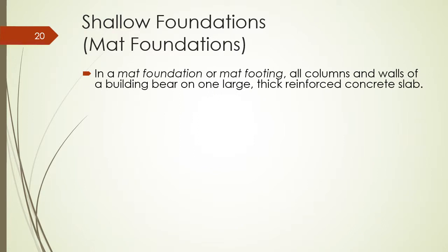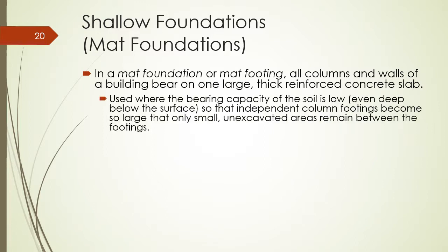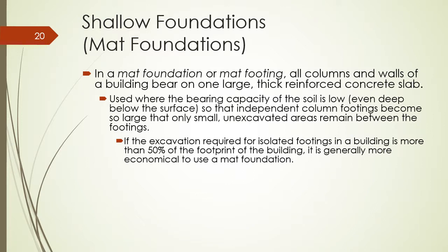A mat foundation, on the other hand, all the columns and the walls in the building will bear on one thick reinforced concrete slab. Here it's used where I have low bearing capacity of the soil, even if it's deep below the surface. So independent column footings become so large that I've pretty much excavated the entire area. So if the excavation required for isolated footers in a building is more than 50%, it's usually more economical to